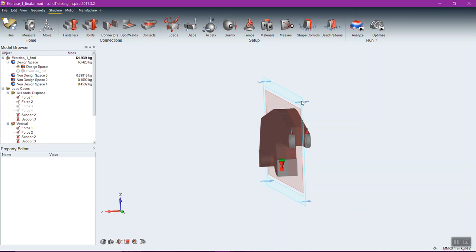Casting or stamping, you imagine you have a flat plate of material, you have a punch on one side and a die on the other side, which is the reverse of the punch. The punch comes down, pushes that material into the die, exceeds the yield strength of the material so it permanently deforms, and you end up with a shape. A large portion of the cars that you drive are made in that way. If you look at your hood, at your body panels, at many of the brackets inside of it, they're made in that way.